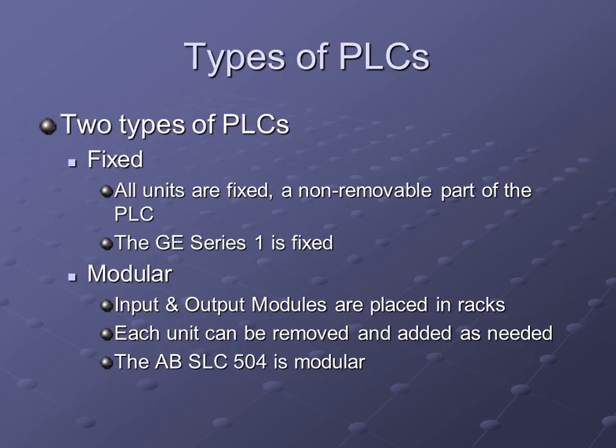But if I need 16 input modules, I just go buy a module. Pop it in there, and now I've got 16 input and 8 output. So this is a modular PLC. This means I can add ports to it. I can add cards that will expand it.